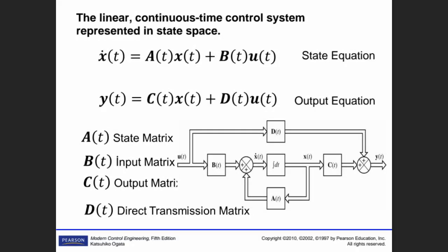That's all we define. And if you write the equations like this, x1 dot, it might be a single input or single state variable, then A is the state matrix, B is the input matrix, and that is the equivalent representation. And you need two equations. One of them is the state equation, the other one is the output equation.